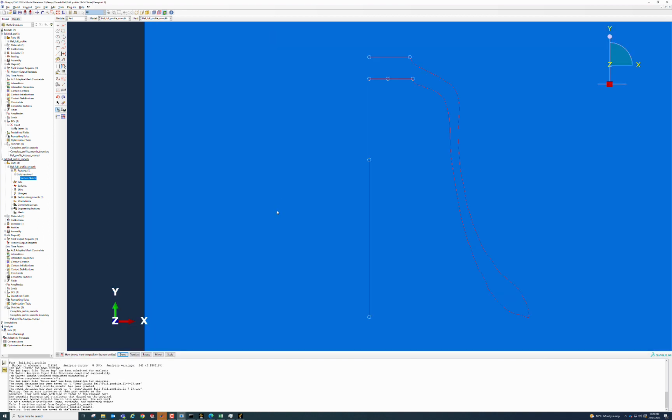And then we can grab that new section, that alternative section. Of course, we haven't regenerated the part yet, so the 3D geometry still sits in the back of the sketch there, but now we have our new profile in here. It's a little bit different. Some of these endpoints aren't joined up. We've got a line here indicating the axis of symmetry, so we'll need to edit that a little bit, which I'm doing now. Remove that line for the moment.